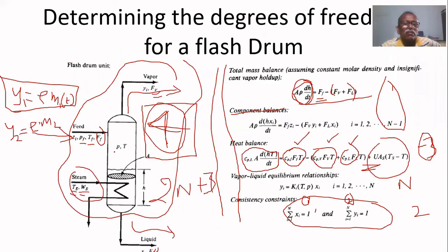In this distillation column, we have to maintain P and T, because you know that P and T are very important. For the boiling point of this top product, the temperature T has to be maintained at pressure P. Because if pressure increases, the boiling point also increases. That's why at this pressure P, this is the temperature required to evaporate this top product. So this P and T are important variables and must be controlled.